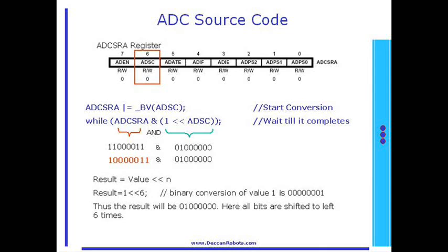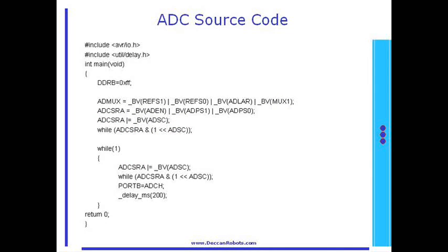The next screen will teach you to read the conversion results. This is the total source code for your application. Connect 8 LEDs to port P and connect a variable resistance to the PA2 pin. If you are using the EDT experiment board, you can make these connections using a connector. If you are using AVR Lit, then these connections are already made for you. The source code will read the ADC value and convert it every 200 milliseconds. The equivalent converted value is shown using LEDs. You can change the input voltage to the ADC channel by trimming the preset using a small tip screwdriver.